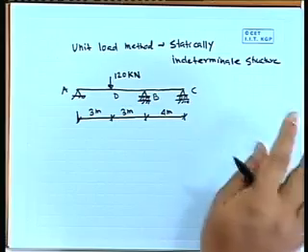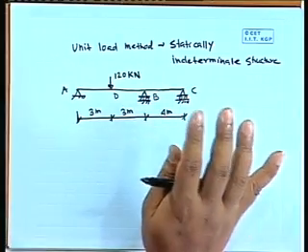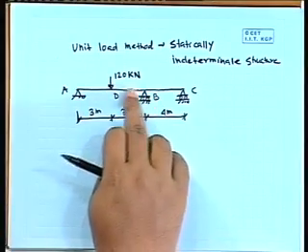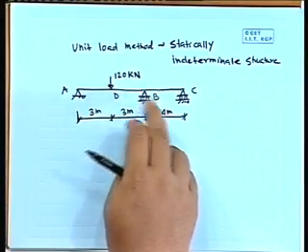If we remove it, it will be a simply supported beam with a load, and only one overhang part will be there. That is a standard typical simply supported beam problem with a central load, with only some overhang part without any load. That problem we know is a determinate problem. So, this reaction is the additional reaction at C. Or, as another option, we can remove the support B, then it will be a simply supported beam with some load at any point. This reaction is the only additional unknown.